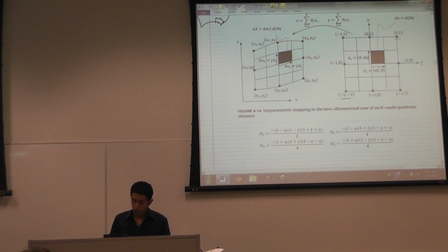shape. Of course, it's very important that if you're using software and you're inputting the coordinates of the elements manually, you have to define it. Now the software does it for you, but during my time when I used to do FEA, I had to say this element is defined from these particular nodes. So I had to input the order of the nodes in the correct manner.